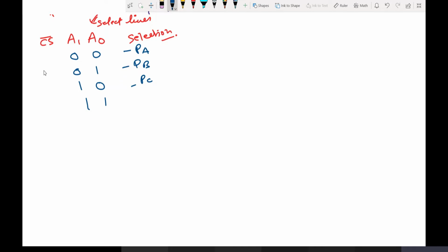Okay, now CS bar is very important with this, because if you want to operate with 8255, CS bar must be provided with 0 all the time. So that's why it has to be taken in this table. If CS bar is 1, there is no A1, no A0, the action is simply 8255 not selected. Fine, and we are missing one thing also here.